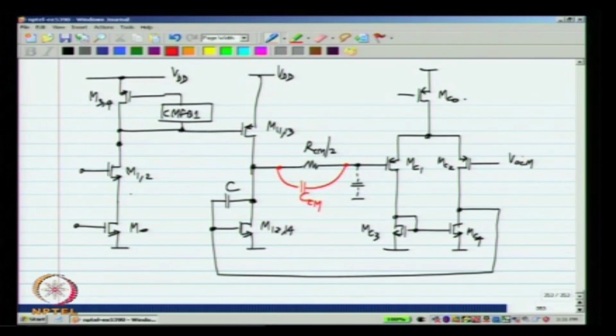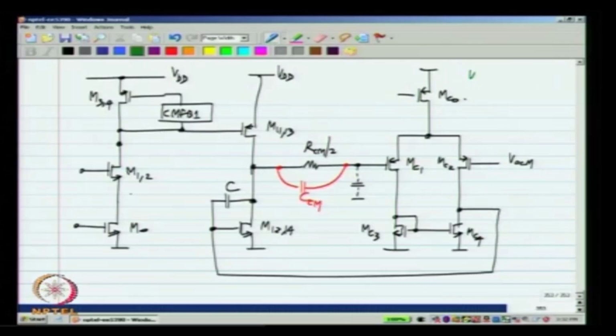Okay. So, as before, the common mode feedback loop, I mean this we have seen in case of the fully differential single stage op amp, the common mode feedback loop itself looks like a 2-stage single ended op amp in unity gain feedback. The first stage consists of the GM formed by MC1 and MC2, and the second stage consists of M13 and M14, which are basically the loads to the second stage in the differential picture. Okay. Now, again we know how to make this feedback loop nice and stable, we know what its unity loop gain frequency is. So, I will not analyze that further. Okay.